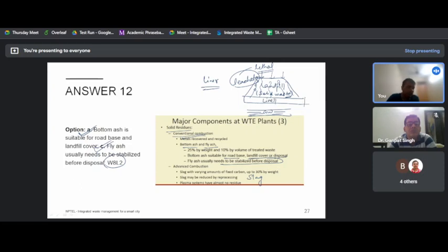For collecting it, we will place a liner. What the liner does is collect all the leachate that is coming, and we can finally store it in a facility. Horizontal and vertical wells will be there. That is the purpose of a liner, to collect the leachate. It tries to prevent the infiltration of the leachate into the groundwater.